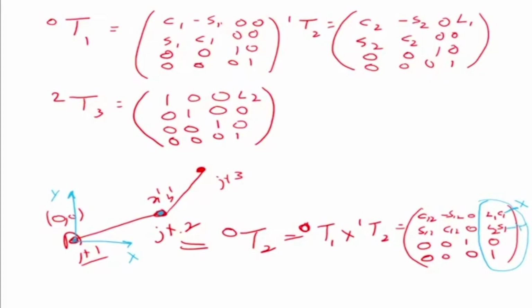Okay, so when it is moving, what we can do is track this point. As theta 1 is changing, L1 cos theta 1, L1 sin theta 1, this point will change, right? So by using this matrix T0 to 2, I can get from the fourth column what this point x dash y dash is. Now for joint number 3, this point x y, how do I get that?